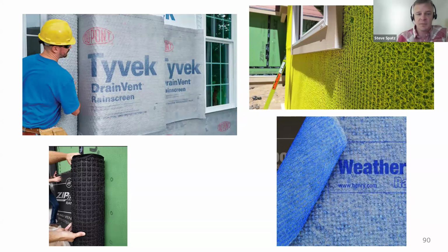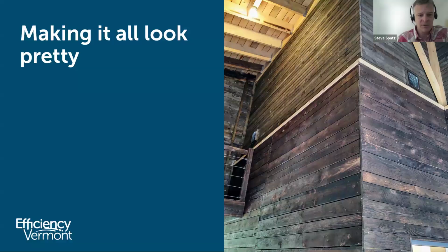And as I noted, the manufacturers of exterior products have all seen what the codes require now, seeing the direction of where we're going, of what creates and makes durable assemblies, but also what the code requires. So a lot more products now that are integrating these drainage assemblies into WRBs and exterior finishes. So really, it's hard not to integrate into assemblies at this point.